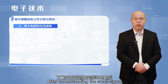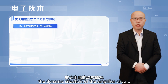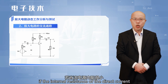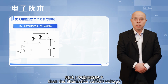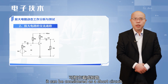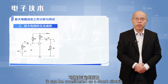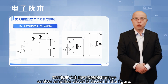After understanding the small signal equivalent circuit of the transistor, let's analyze the dynamic situation of the amplifier circuit. First, draw the alternating current equivalent circuit of the amplifier. For the alternating current path, if the internal resistance of the direct current power supply is very small, then the alternating current voltage drop across it is very small. It can be considered as a short circuit. If the capacitor is passing alternating current and the voltage drop is very small, it can be considered as a short circuit. An alternating current path of the common emitter amplifier circuit is shown in the figure.